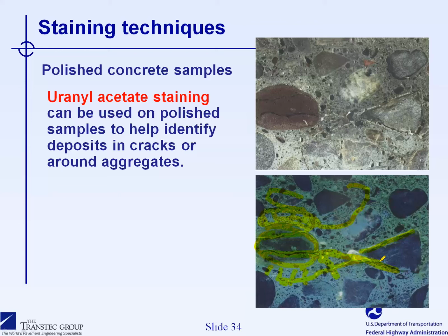But once again, this is still to be proven to a large extent, because right now we have not carried out a lot of testing for determining the water-soluble alkali content in concrete incorporating large amounts of SCM. The main reason being that concretes containing such a large amount of SCM generally don't show signs of ASR.